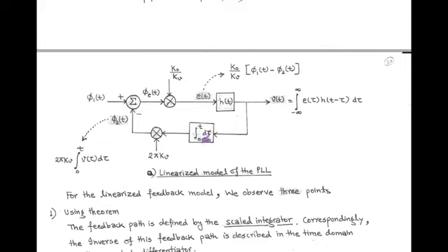In this, the input signal is Vt, that is a control signal. So the output of this transfer function is integration of V tau d tau with a limit of 0 to t. And after multiplying with 2 pi into kV, we get 2 pi kV integration of V tau d tau. That is the value of phase angle phi 2.